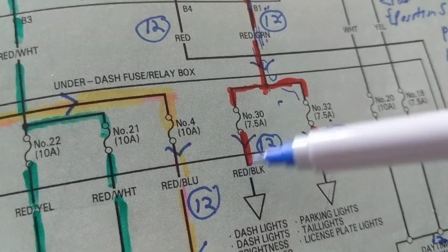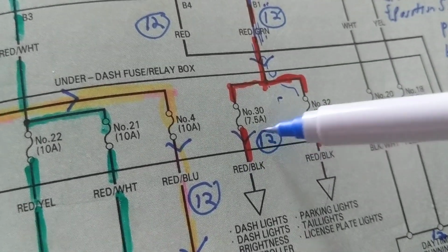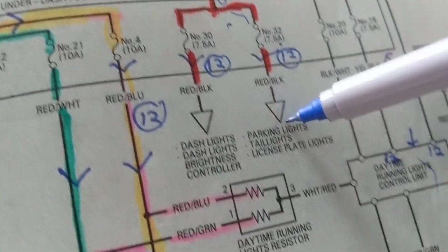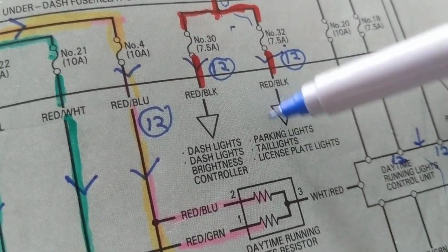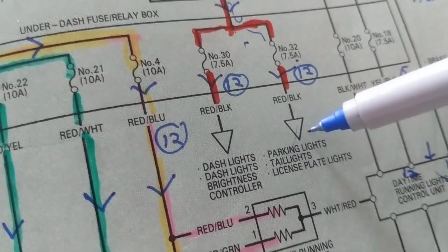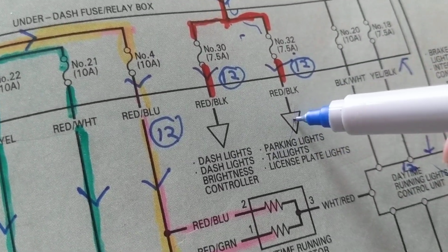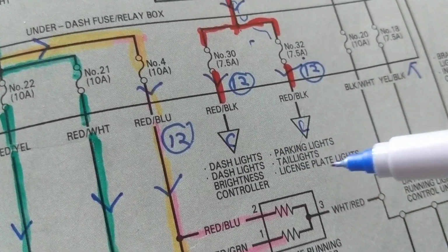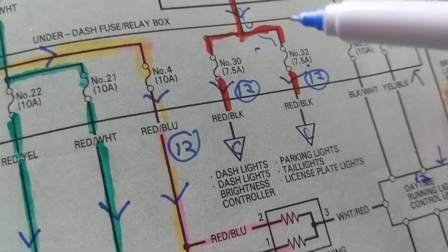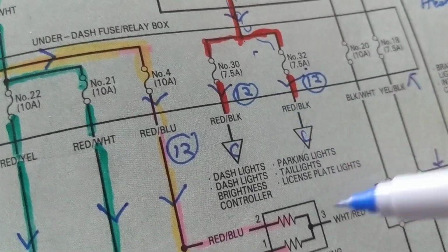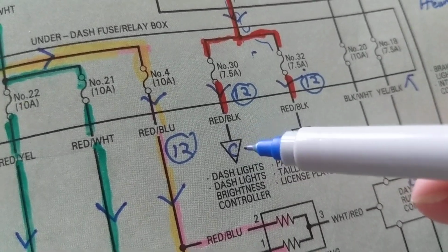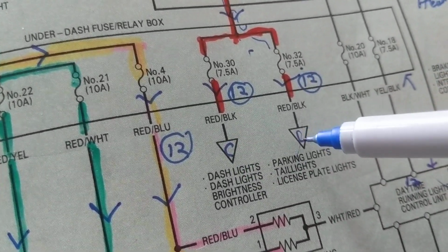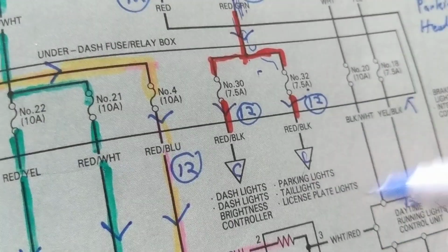Okay? How much current will divide? Has to be less than 7.5. Maybe it's 6 amps, maybe it's 5 amps, we don't know. So red and black. And what is this? Remember I showed you, this is not an antenna. This is another part of a circuit. So if the other part of the circuit would be C, we go look up the other part of the schematic where it says C. That means it's a continuation. We don't want to put too many lines, so we just cut it short and we denote it with a triangle like this. That means it's understood. It's continued on another part of the schematic.